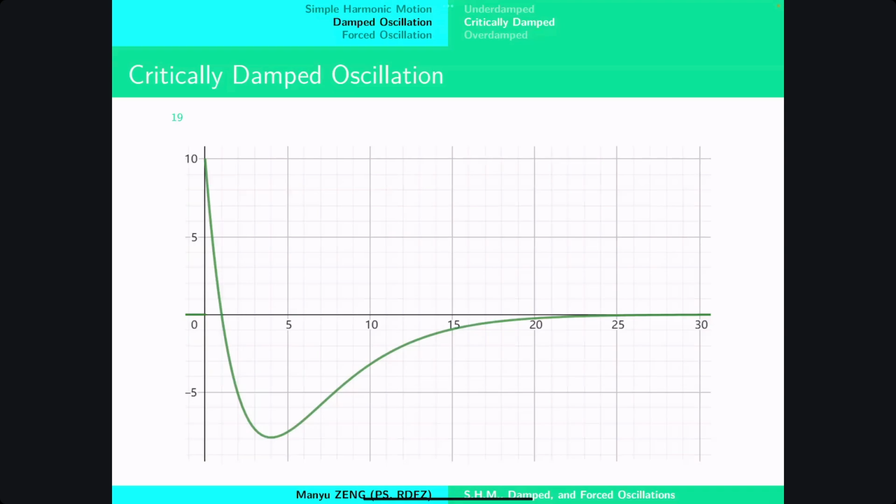So we add some damping on the scale, and if we add underdamping, the oscillation is underdamped. Actually, it still oscillates, but it decays rather slowly. But in this case, if we add damping that is critically damped, the reading of the scale gets back to its real value as soon as possible. So it is desirable to add critical damping on our system.